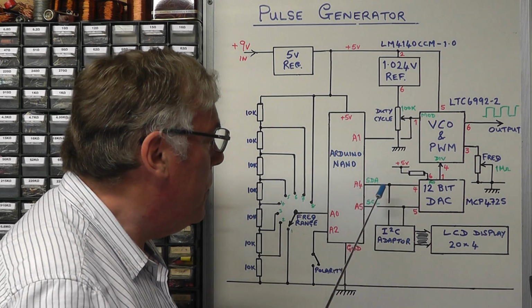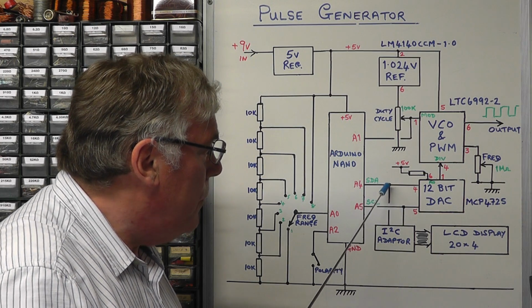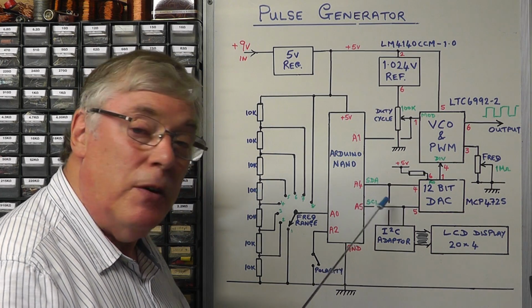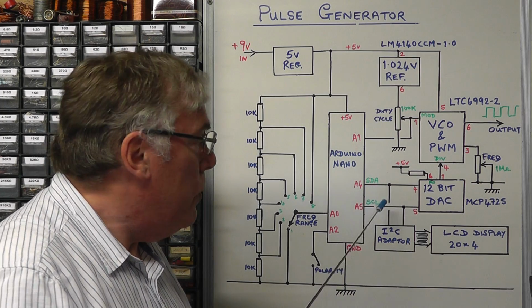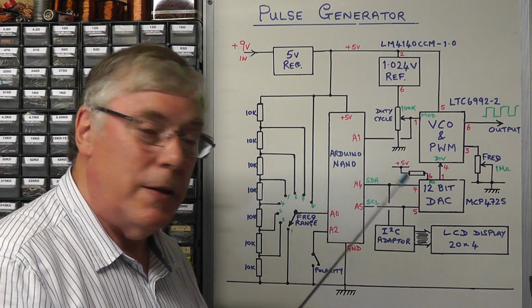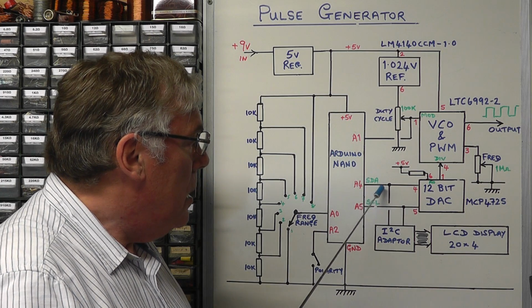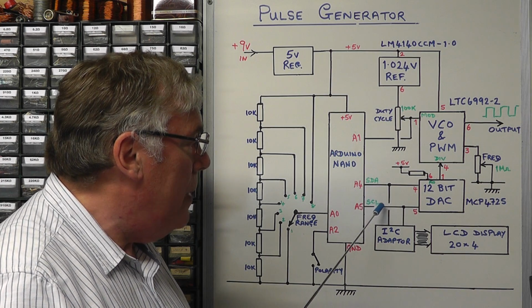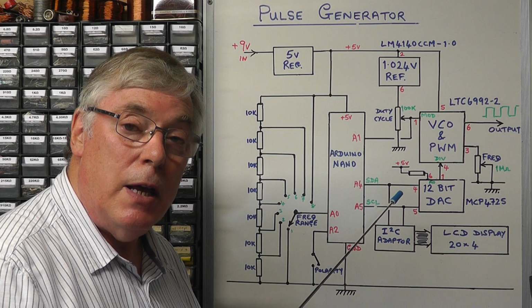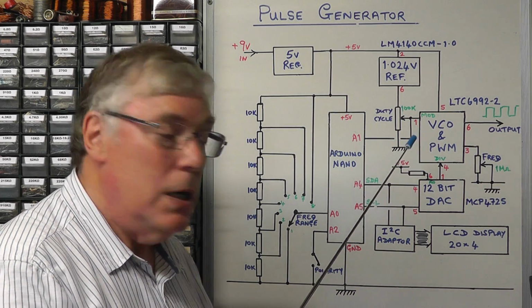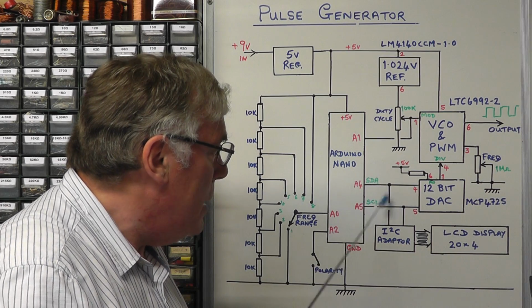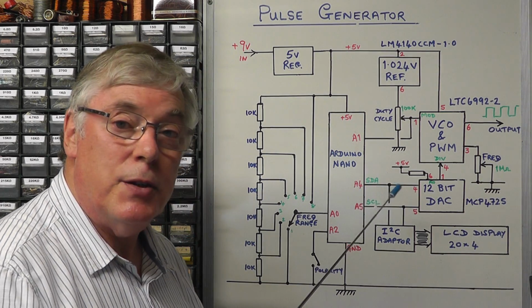the Arduino Nano. Now, in order for the I2C bus to function correctly on the data and the clock lines here, we need to have a couple of pull-up resistors. I've not shown them here, but from A4 and A5 I'm going to use 10k resistors going from those pins to +5 volts, and that just pulls up those pins high on the I2C bus.